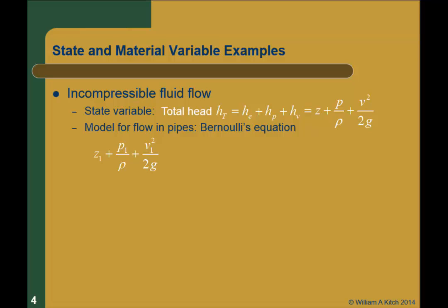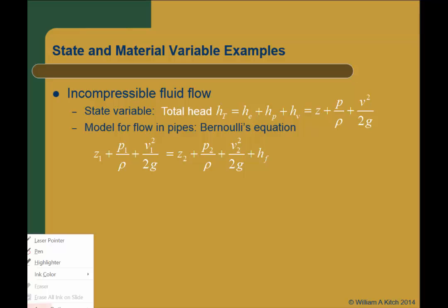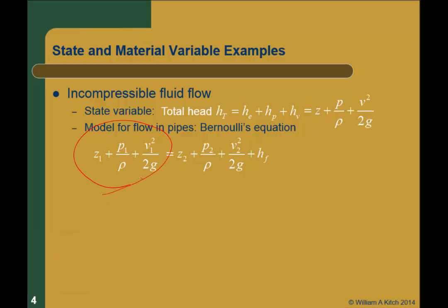this represents the total head at one point. Then that's got to be equal to the total head at another point, point 2, plus whatever losses there are between the two. And we have all kinds of models for the losses. Okay? So that's something we all know.